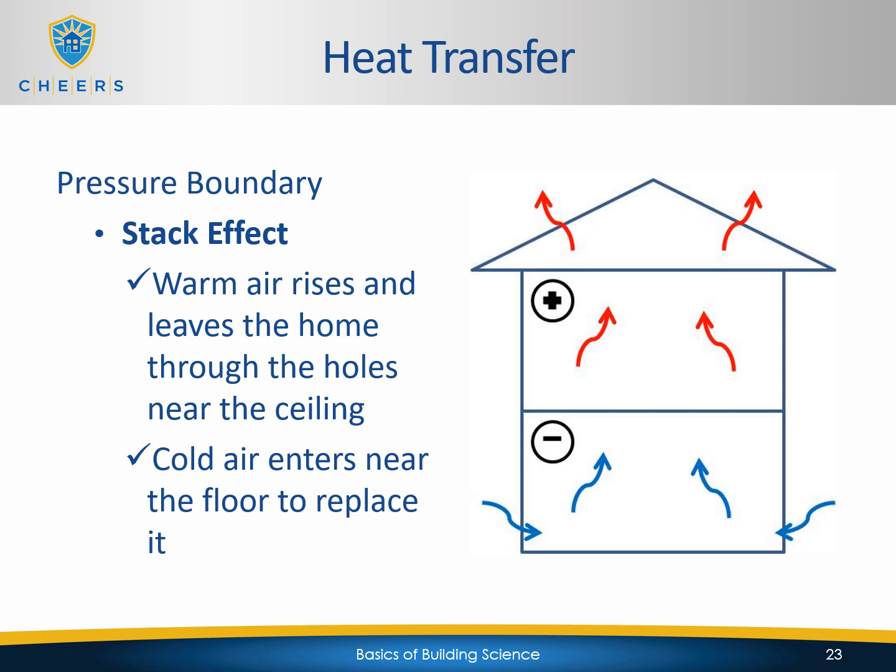When it comes to air movement in relation to building design and building operations, stack effect is directly related to that. Warm air rises and leaves the home through the holes near the ceiling. Cold air enters near the floor to replace it. Cold air is denser and comes in from the bottom, being sucked in at the bottom of the house. This could be the case also in a single story home, by the way. It doesn't have to be a multiple story home for this to work. But the higher the building, the more stack effect is going to be present. Nonetheless, you could have the stack effect in a single story house too.